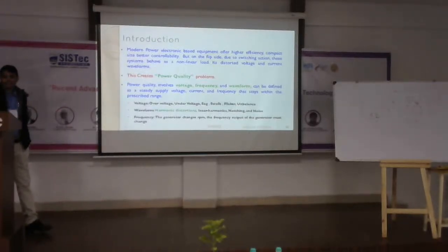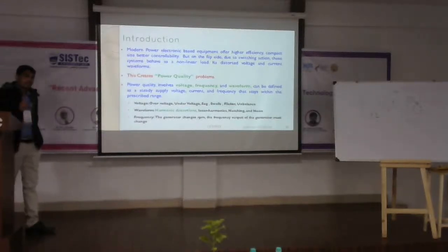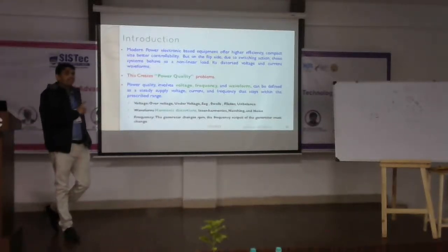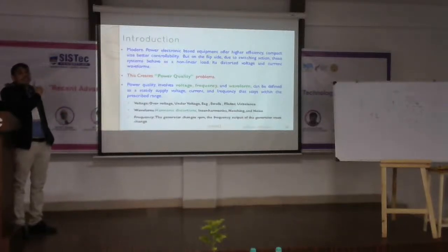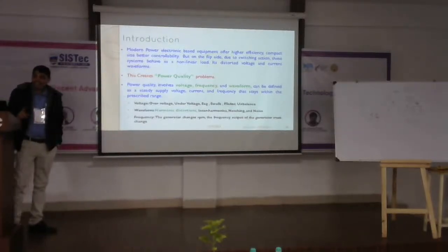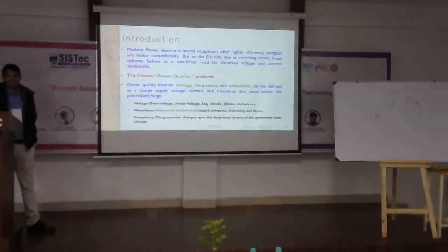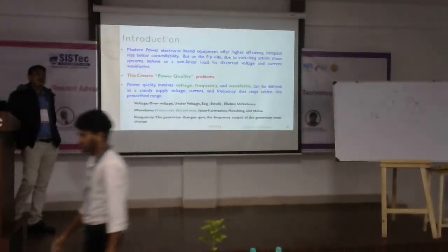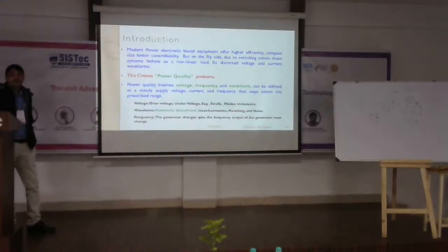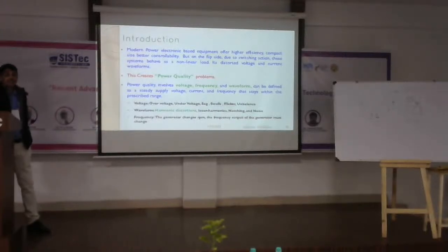Sources of harmonics are the rectifier and inverter. Again we are talking about the converter, which is already used in the electric vehicle. Static VAR generators are there. Switching power supplies, as I told you a little while ago about what systems create harmonics, that is the SMPS. That will create harmonics. DC motor drives, adjustable DC motor drives, means the washing machine and also the fridge.